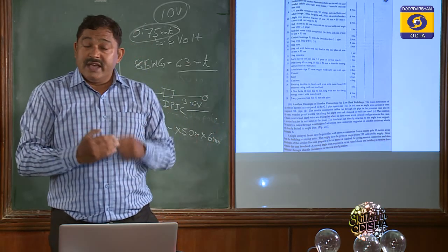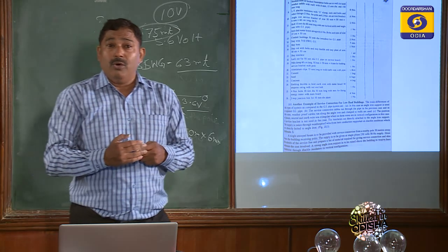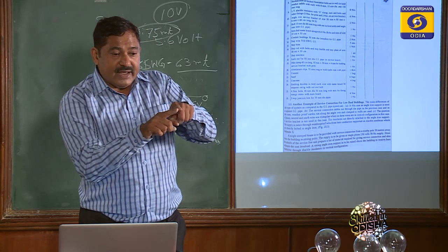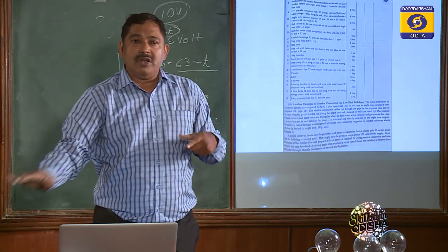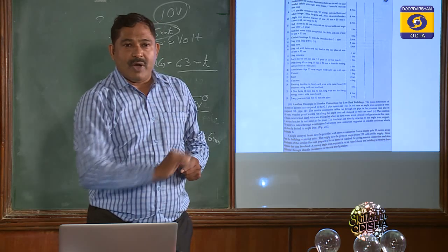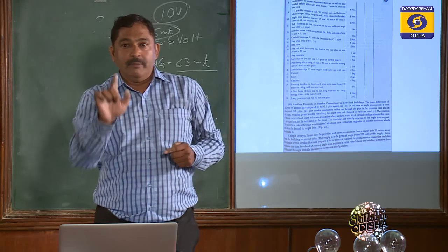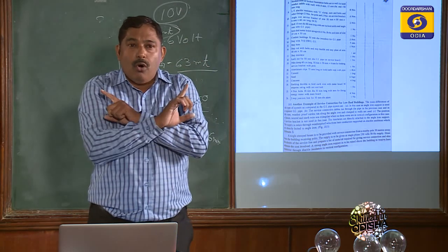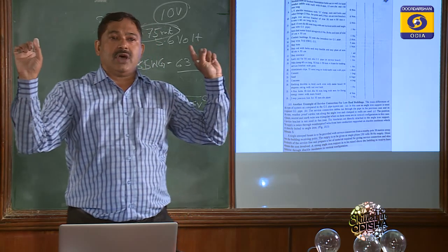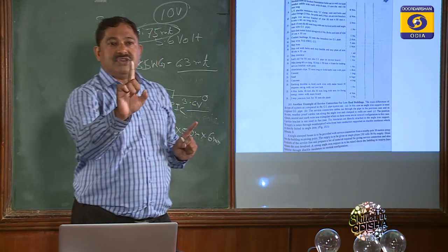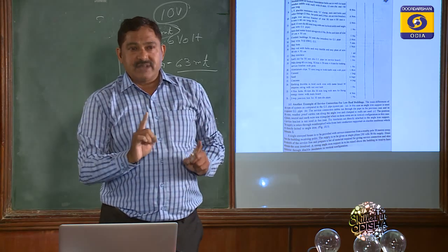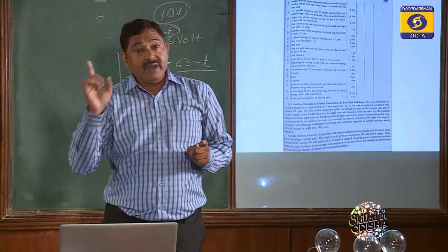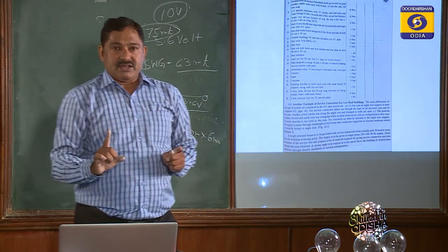And nowadays this MCB is not for overload only. In addition to overload, there is RCCB, which works in case there is an earth fault. If a small child goes and touches a phase wire and immediately gets a shock, the supply will go off immediately because of this RCCB. No human being will get any shock in any household if you have an MCB with RCCB. These are a bit costly, that is why people normally don't purchase them, but they have tremendous safety measures within.